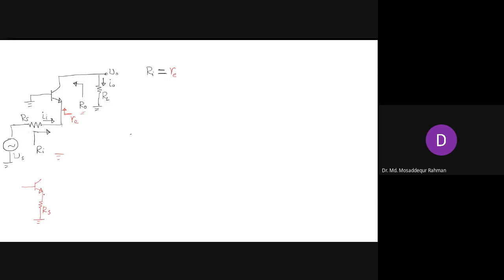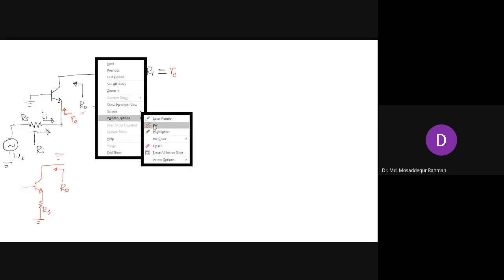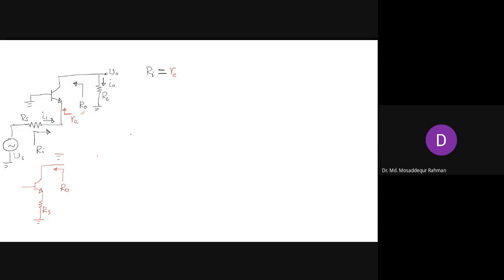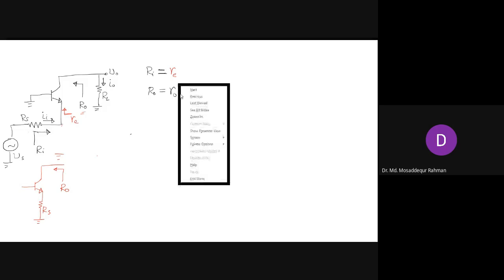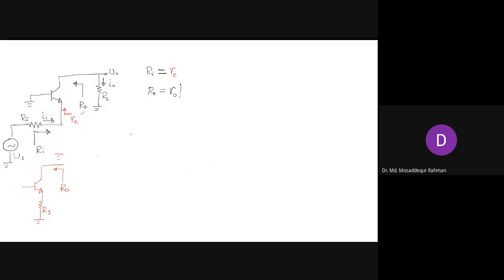So if you have a circuit like this, you have a resistance in the emitter and from the collector side. For this circuit, we didn't show the derivation because it's not important. It will take one whole class, not worth it. So if you are looking from the collector and you have a resistance in the emitter, then the output resistance is given by R naught multiplied by a complicated factor, as you have rightly said. And that complicated factor has just two terms, not that complicated.